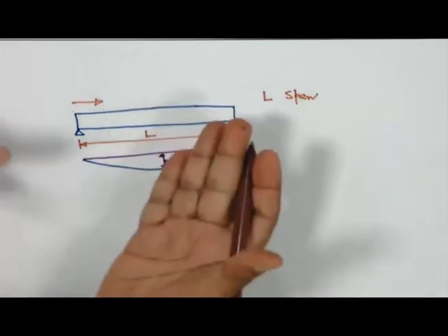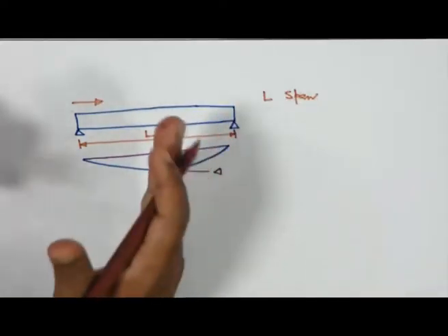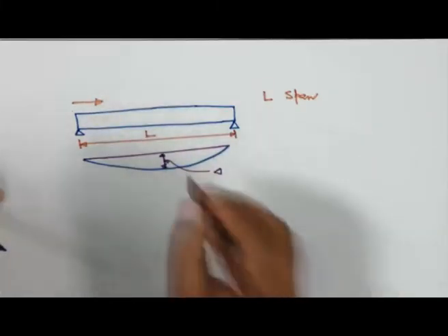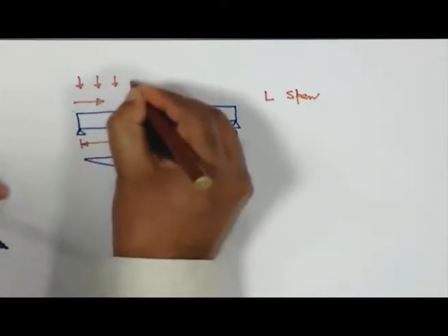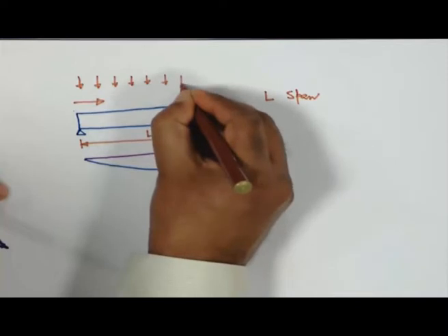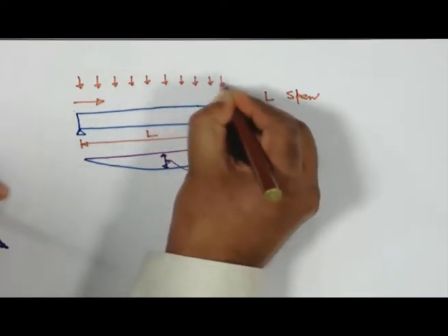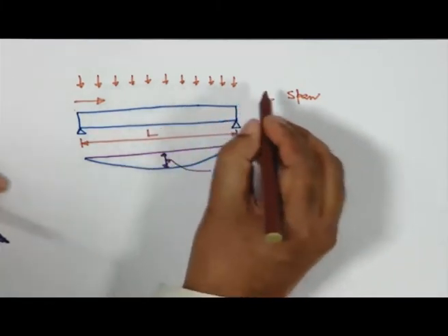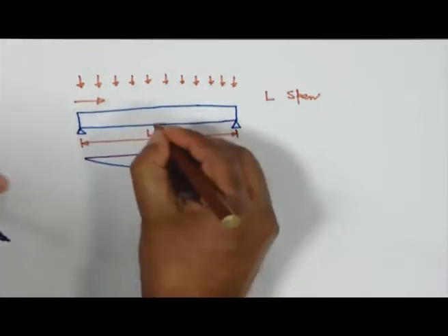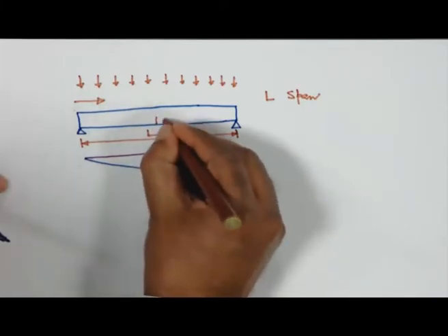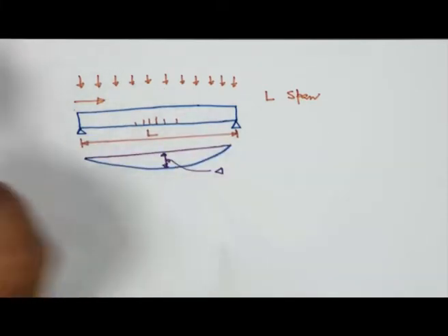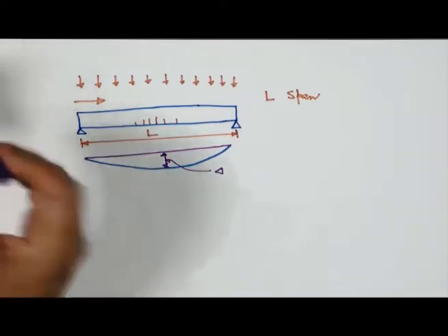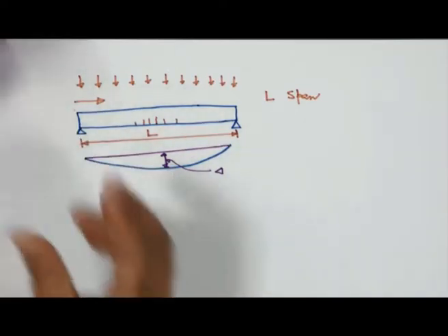I told you in the very beginning, the tensile strength of concrete is ignored. The stress block can be a rectangle or any other shape, provided the prediction of strength is in agreement with the results of tests; rectangle also, trapezoid also. For design, gamma m equal to 1.15 is used for steel, and 1.5 for concrete. In tension, please note it, irrespective of this, how is it decided? Proportion of cement, coarse aggregate, water cement ratio.